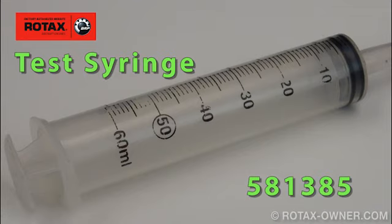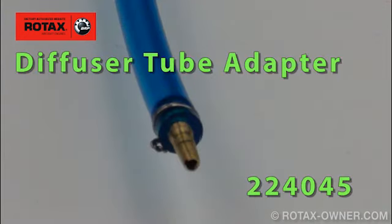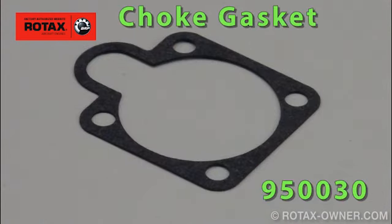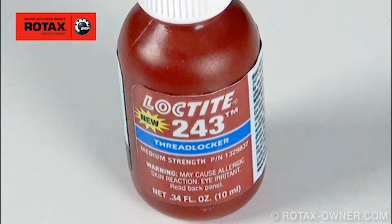The following parts and supplies will be required for this inspection. 1 test syringe, part number 581385. 1 oil line, 150 mm, part number 960043. 1 diffuser tube adapter for connecting your test tool to the carburetor, part number 224045. 2 choke gaskets, part number 950030, and a small quantity of Loctite 243 thread locker.